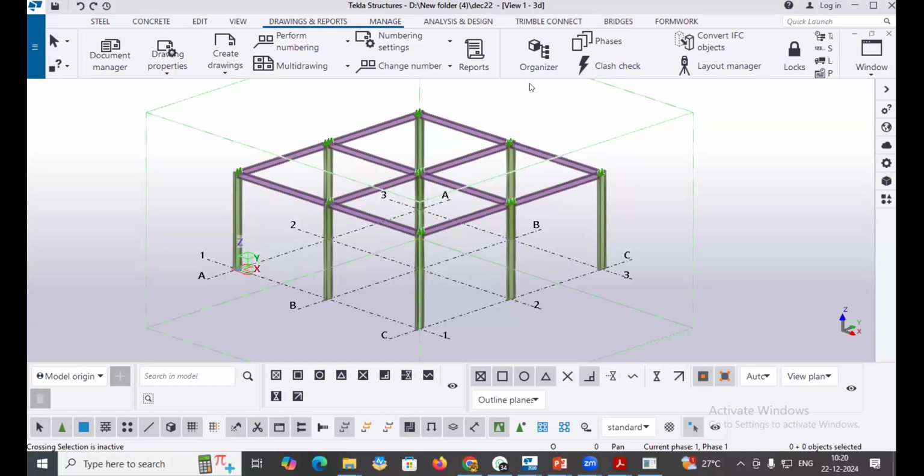Right now you can only use SAP, ETABS, or STAAD.Pro for designing steel structures, because only there can you see the forces visibly, extract them, and give the justification. In Tekla Structures it is still in R&D. There is no other proof they can provide like STAAD.Pro, ETABS, and SAP. For marketing purposes they are telling that they can do all kinds of analysis.